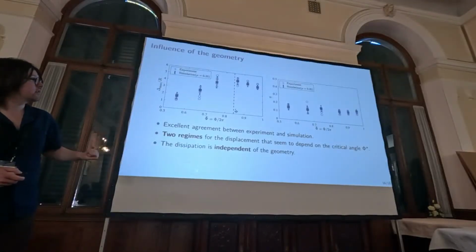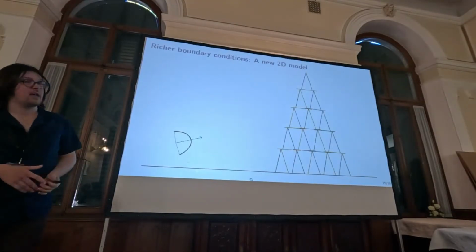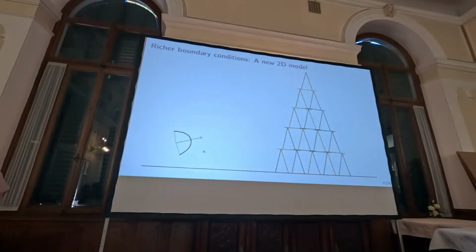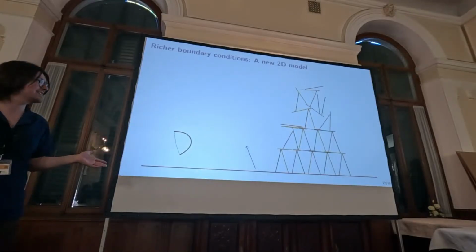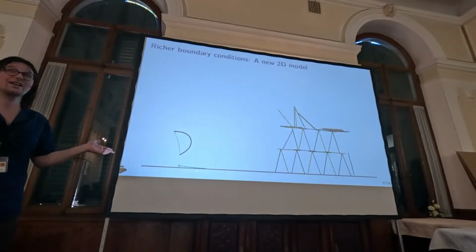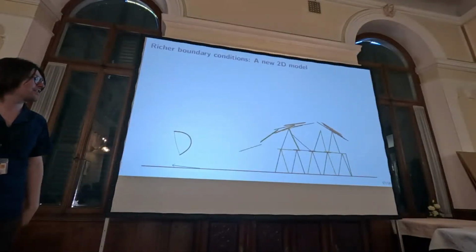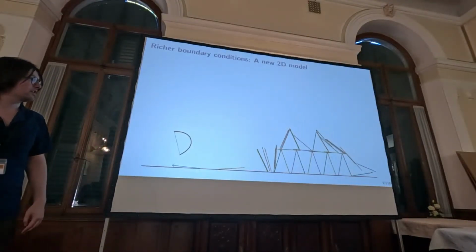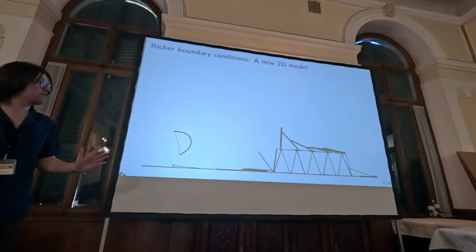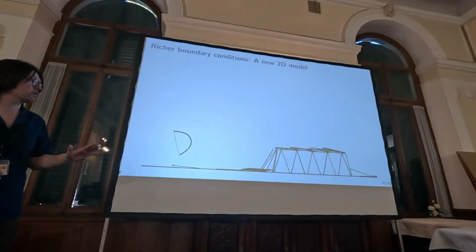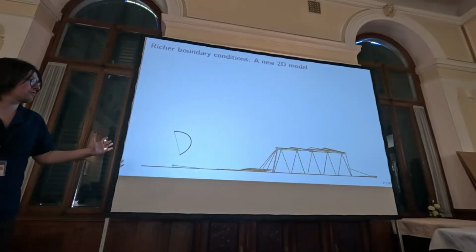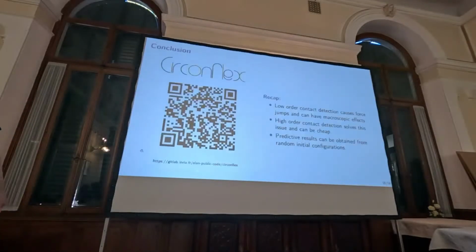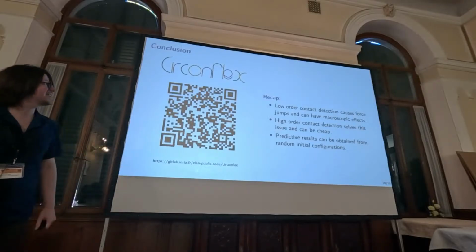Maybe just to give a quick update on the latest code I've been developing about a 2D model. I've improved the 2D rod model, mostly for computer graphics, but still we have validated it physically, and we can do funny real-time experiments. It's mostly interactive on the computer. It's the same projective Gauss-Seidel method to solve the contacts and first-order semi-implicit time integration, but it works quite well in practice. And if you want to play with this model as well, there is a code that has been recently released. It's still a work in progress, but if you want to test it, it is available.